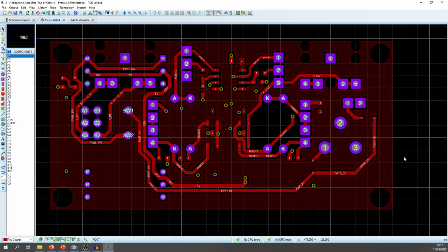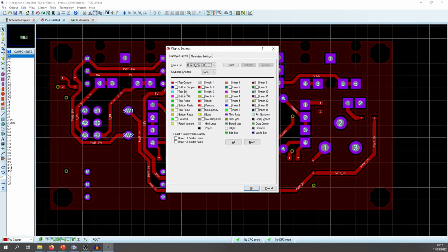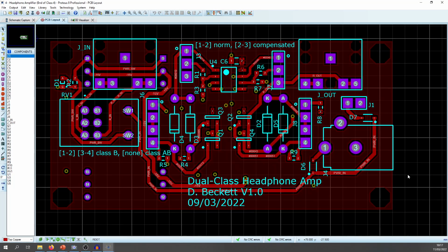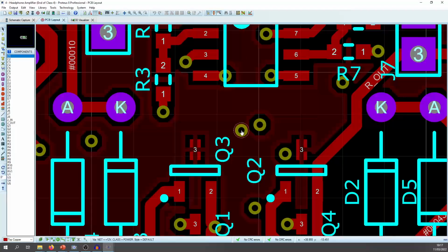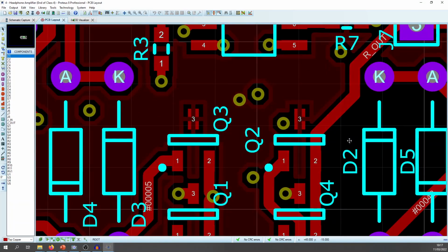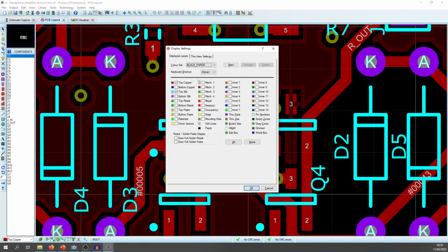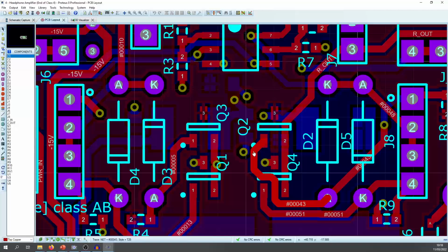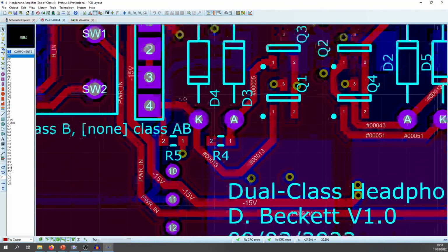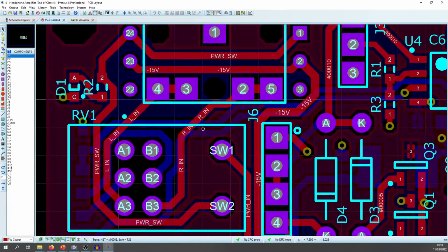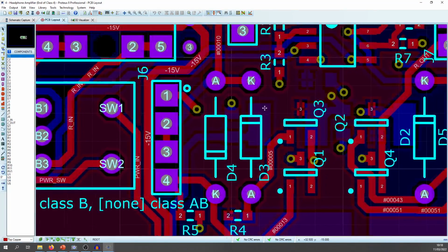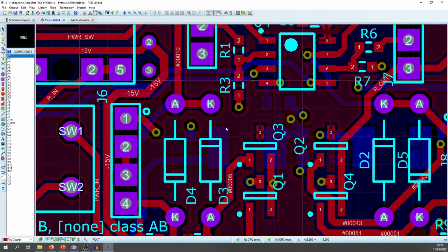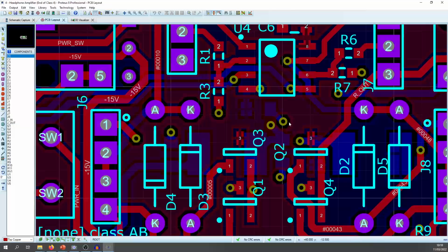there's your top layer. You can just use that on its own. It unconfuses the entire situation. You can even put your top silk back on and you can see where all the components are and what places to avoid. You can't see where the components on the bottom are. So if I put the bottom layer on now you've got a rough idea of what can interfere with what, but like I say, you can imagine it gets a little bit confusing. But it's manageable. Once you get an idea of this, placing components on top and bottom, it's manageable.